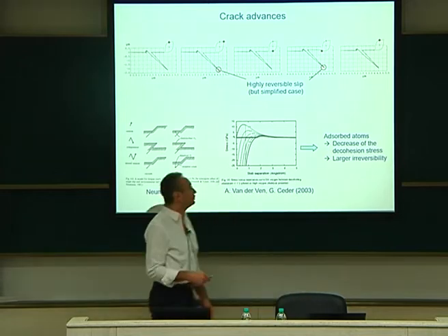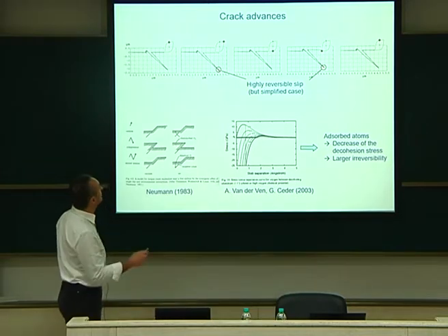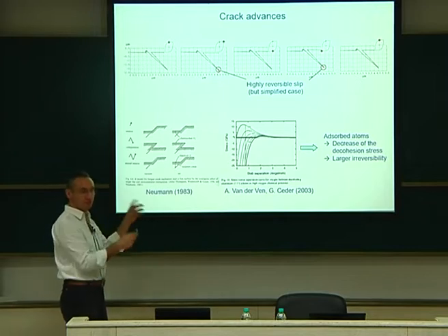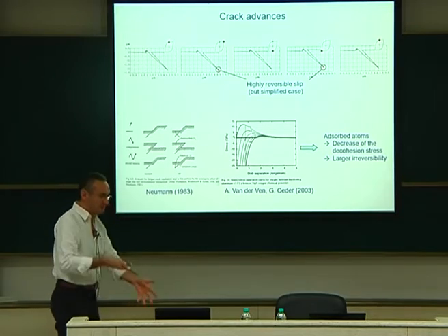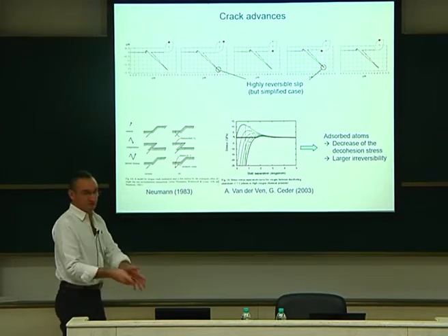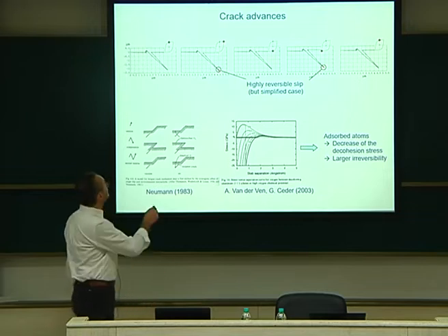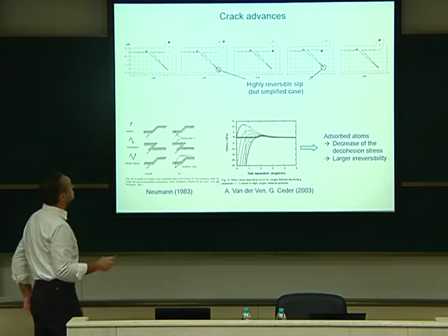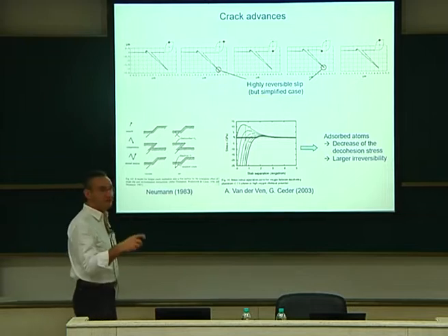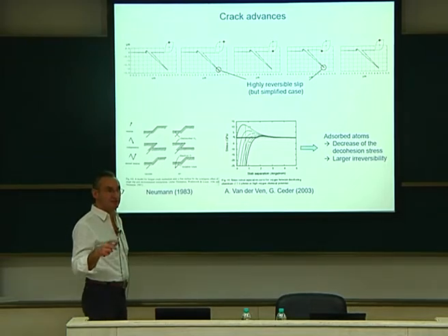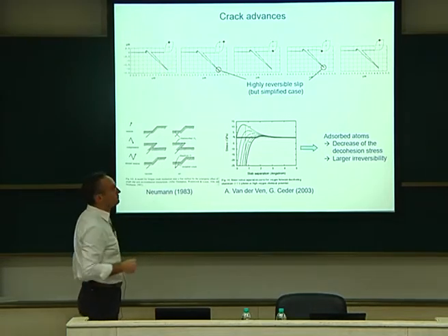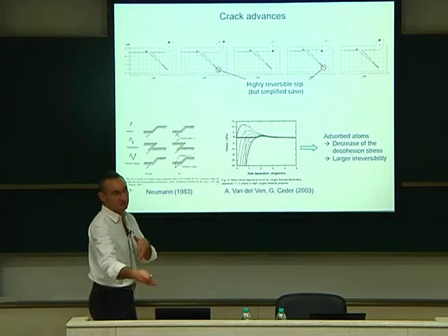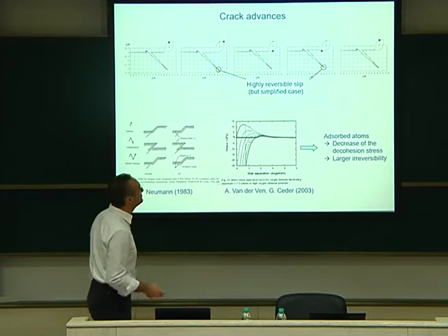So from that now we can compute the crack advance. So how fast your crack could advance. That's the first case, of course, with the PSB: you have your PSB, you put the crack. We saw that this could be compatible. Is this increasing the crack advance or decreasing the crack advance? So to do that, we compute what people call the crack tip slip displacement, CTSD. It means that at the tip of the crack, we compute the displacement field due to the dislocations, and we see if it's bigger or smaller, how it moves with the cycling.